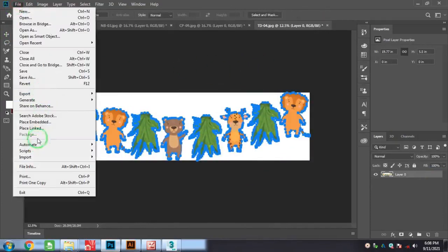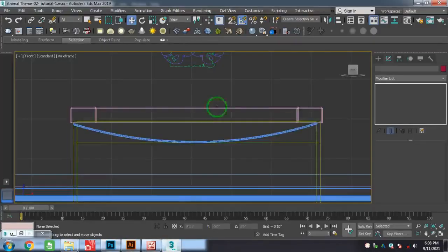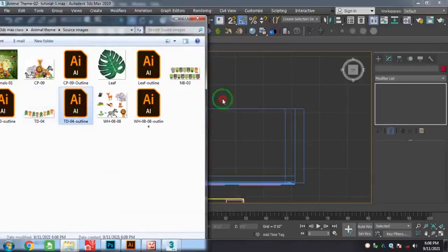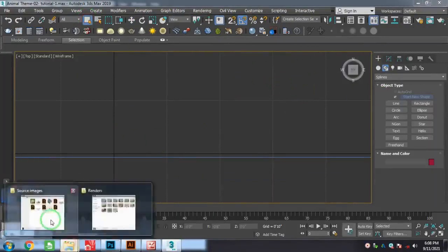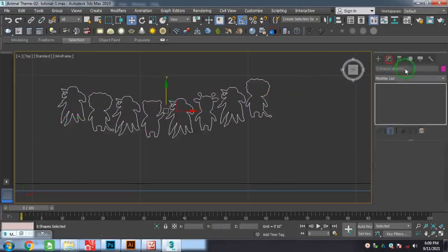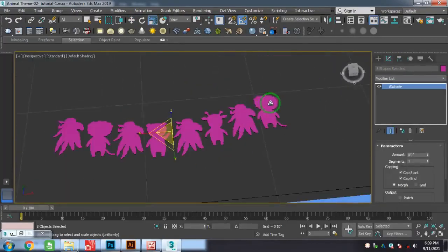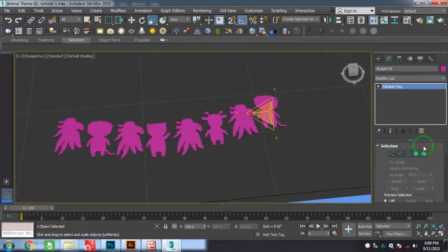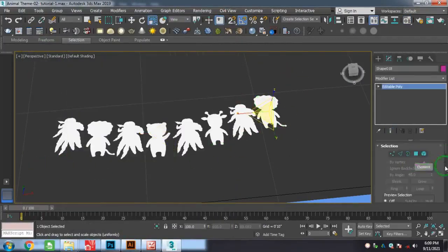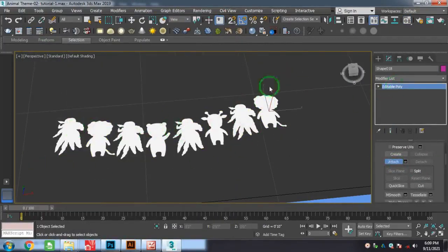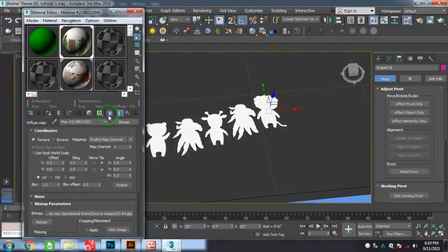and you just open this outline in 3ds Max, and you just select all, just disable this enable in viewport and enable in render, and you just select all and extrude, and you just attach all and give that animal shader to this. Press M for material editor and you just apply the texture to this mesh, and you just give UV map here.